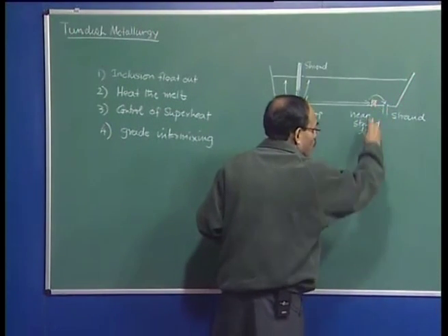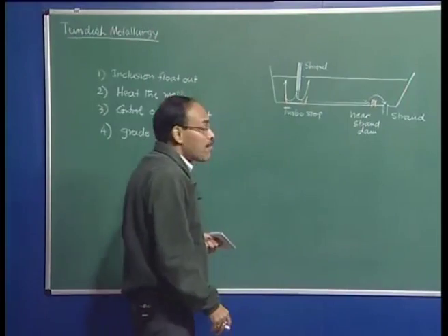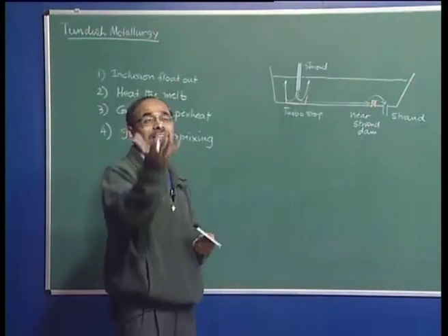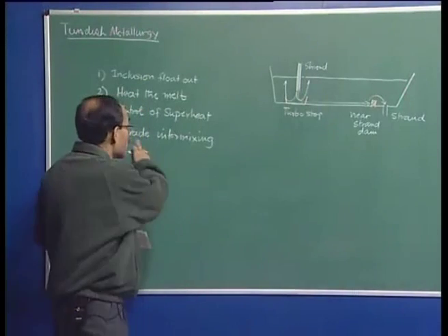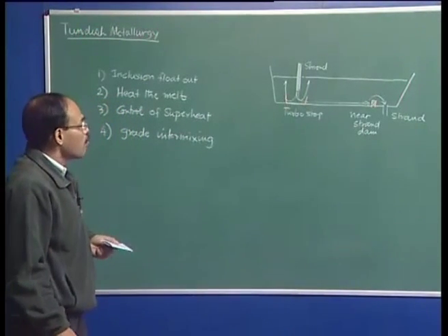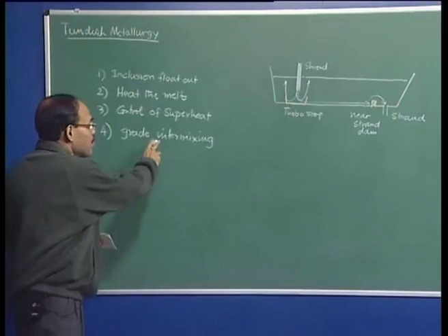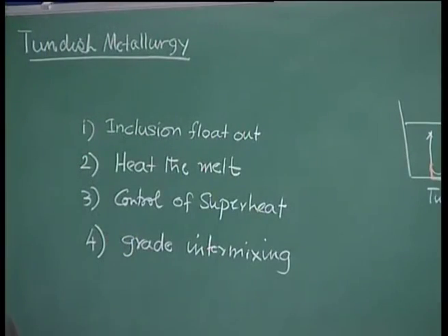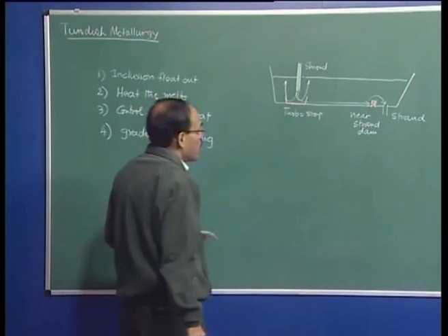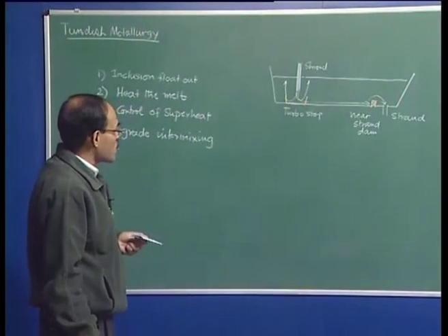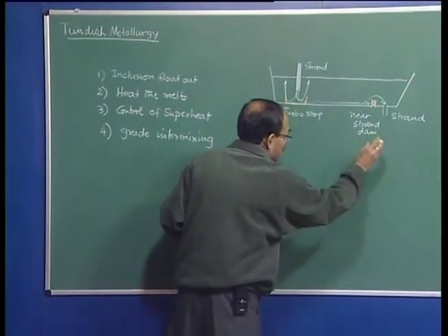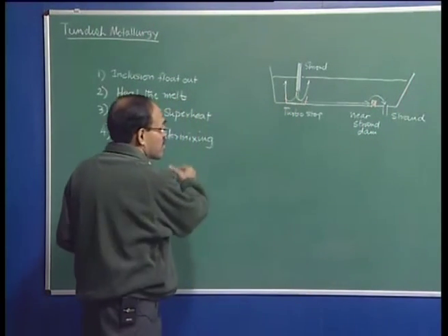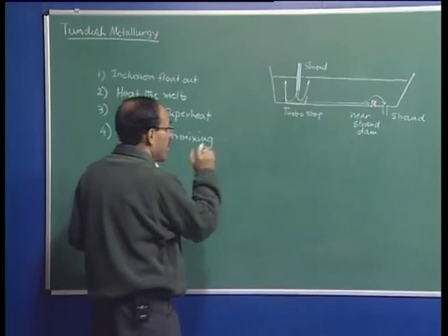will form billets or blooms or slabs which are going to have composition neither of the previous grade nor of the former grade, but an intermixed grade, and that is why grade intermixing is a very important aspect, because intermixed slab, bloom or billet are often downgraded. So, therefore, to improve the performance of the cast shop, we want to have as low a transition slab volume or mixed slab volume or mixed bloom volume as possible.